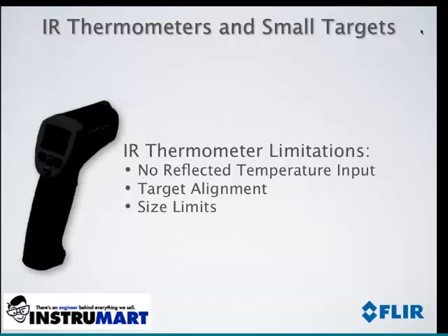But what we learned in that webinar was that IR thermometers, while they have an input parameter for emissivity, do not have an input for the reflected temperature, and reflected temperature and emissivity are both parameters that are utilized to calculate temperature accurately with an infrared device.